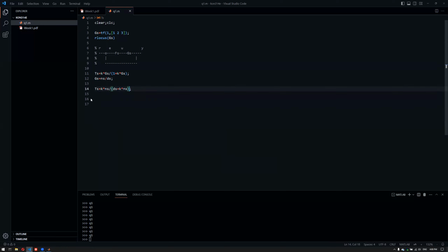Now, the denominator of this here is basically the characteristic polynomial, Pc(s), of the closed loop system, which is quite important for us. Because when we have a certain transfer function, we take the denominator and look at the roots of the denominator. If those roots are on the left half plane in the S domain, then we call it a stable system, a decaying system.